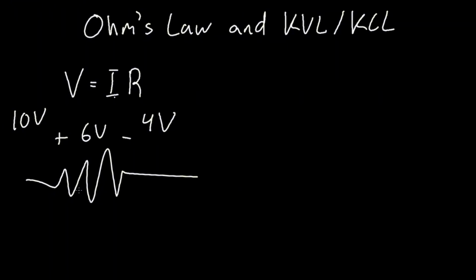And that can be calculated by multiplying the resistance, or the amount of ohms in the resistor. Different resistors have different amounts of ohms. You can have 5 ohms, 5 kilo ohms, 5 mega ohms, or 4.2 kilo ohms. Basically, you multiply ohms by the amount of current going through your resistor, and you get the voltage drop due to the resistor.